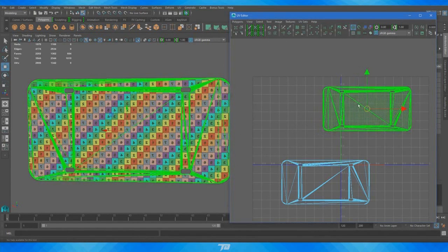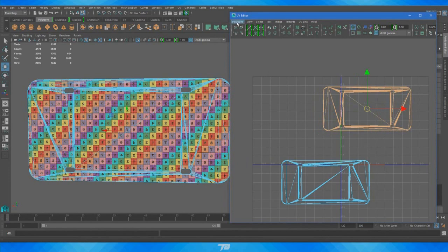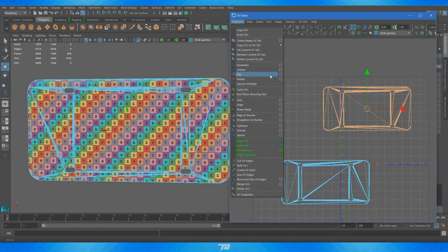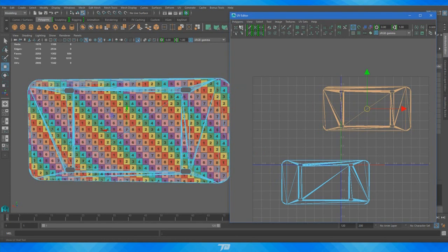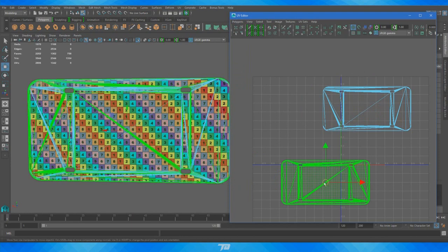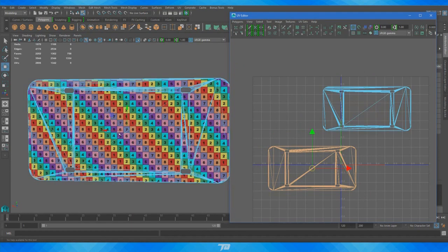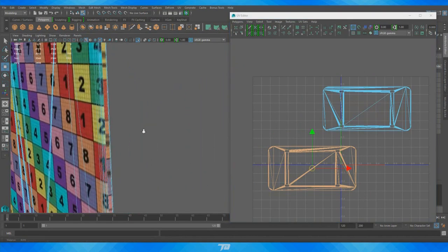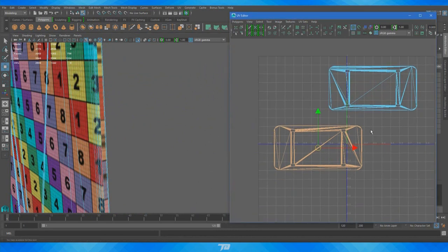And as you can see, everything here is reversed. So I'm just going to have this shell selected, go to polygons, and flip, and it's going to flip it for us. If yours is flipping vertically, just make sure you go into the options by pressing this little box and making it go horizontal. So the only other thing we really have to do is stretch this out a little bit, just because the edges are not as perfect as they could be. We could technically leave it the way it is right now, but it's not exactly where we want it to be.